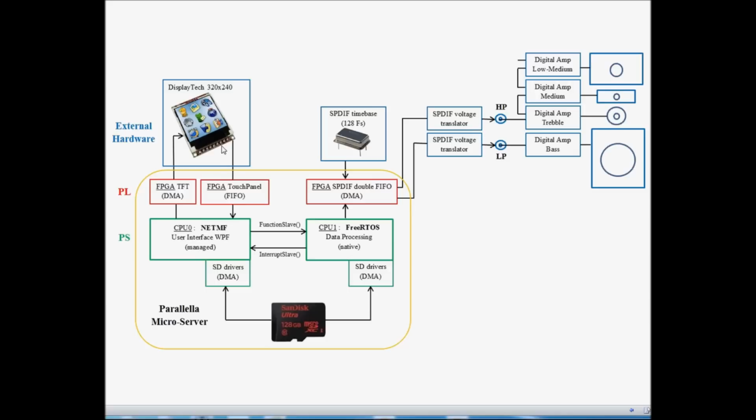The external hardware up to the SPDIF output connectors is limited to the bare minimum. Not shown here, but there is a simple resistor divider for the touch panel, a low jitter oscillator for the SPDIF time base, and 2 simple voltage translators to output SPDIF.